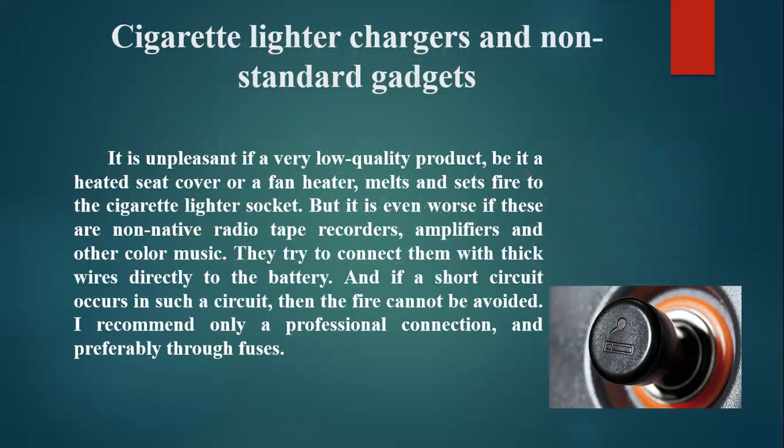Cigarette lighter chargers and non-standard gadgets. It is unpleasant if a very low quality product, be it a heated seat cover or a fan heater, melts and sets fire to the cigarette lighter socket. But it is even worse if these are non-native radio tape recorders, amplifiers, and other color music. They try to connect them with thick wires directly to the battery. And if a short circuit occurs in such a circuit, then the fire cannot be avoided. I recommend only a professional connection and preferably through fuses.